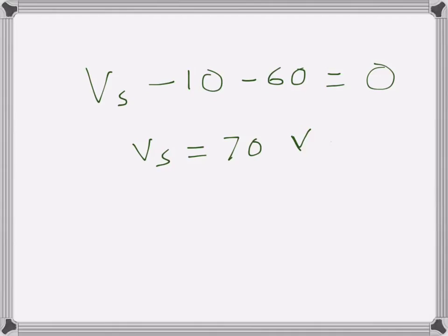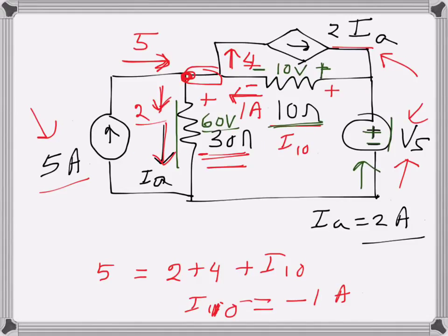So that we know. Now we need to find the power delivered by this source. So what is the voltage, what is the current through this voltage source, we need to find out. And that is probably simple because we have an entering current here which is 4, and we have a leaving current here which is 1. So what we notice is the current has to be 4 entering here, 1 going in this direction, so 3 amps current will go in this direction.